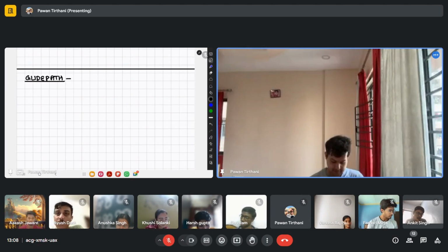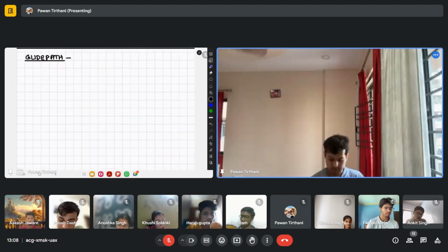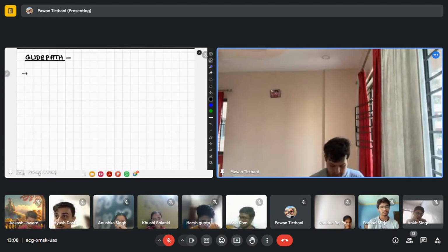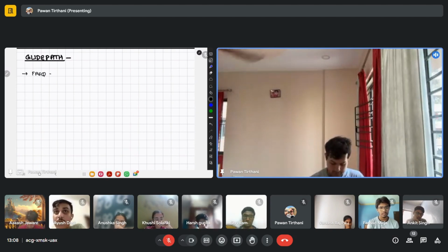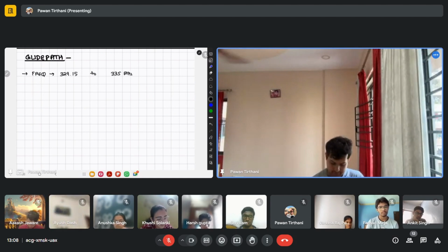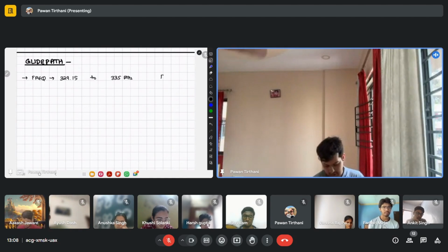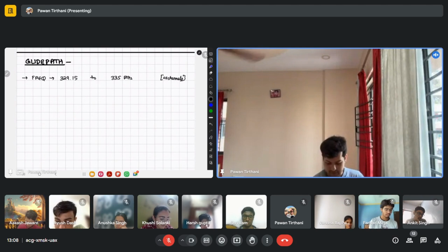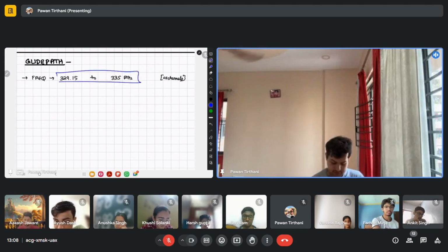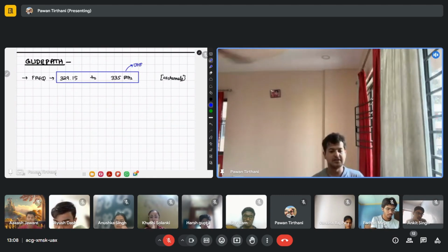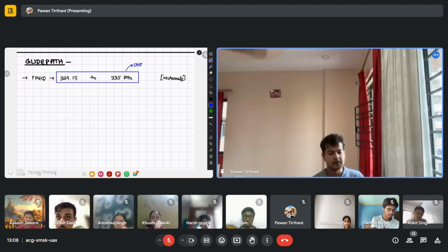You have the ILS glide path. What is the frequency band that it operates on? 329.15 to 335 megahertz. How many channels are available? Again, 40 channels are available. Why are 40 channels available? I'll tell you in a brief moment. Which band do all these frequencies come in? They all come in the UHF band.